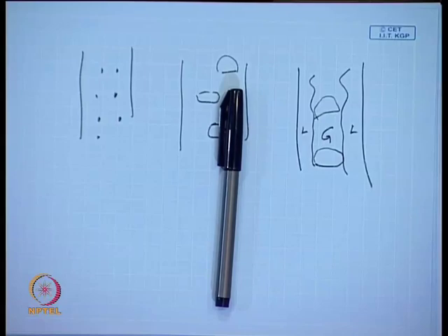Now, let us see under which circumstances we cannot use it at all, even if the two phases are completely mixed with one another. I agree, but it is flowing, maybe through an orifice or a very short nozzle. Under that circumstance, what do you expect is going to happen? Completely mixed flow, but flowing through a very short nozzle or an orifice. Orifice means an abrupt contraction. Then what is going to happen? Rapid acceleration will take place.